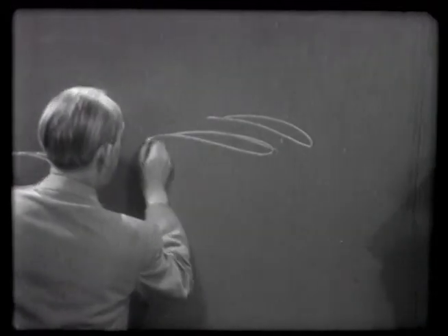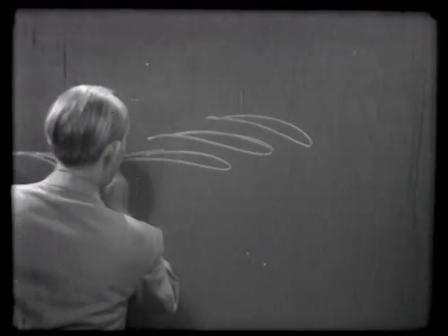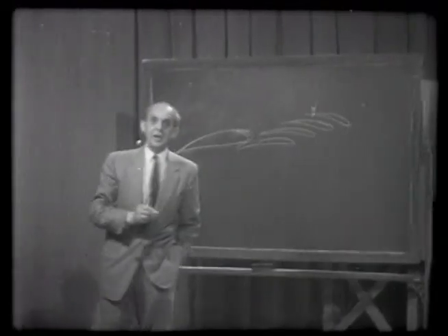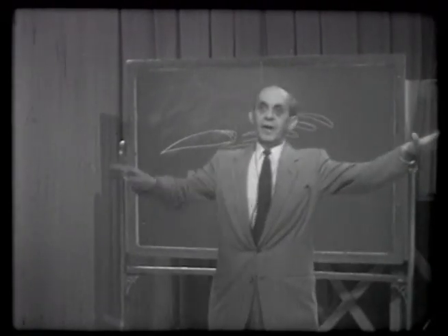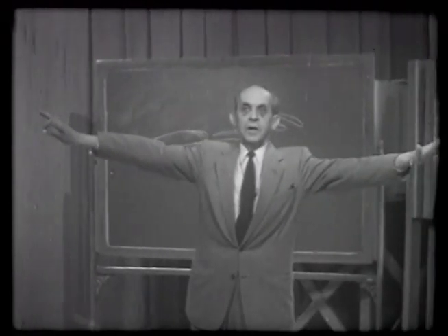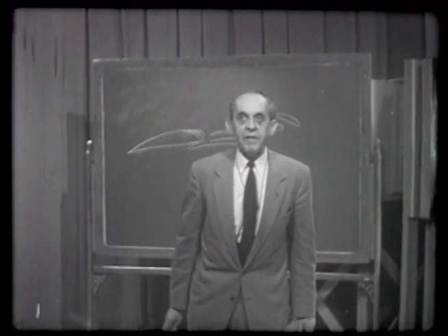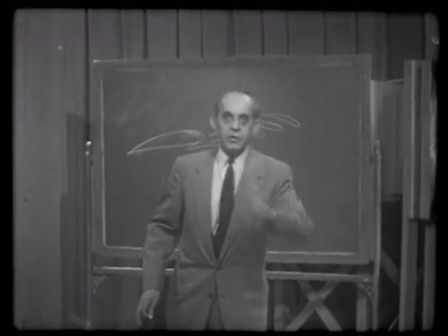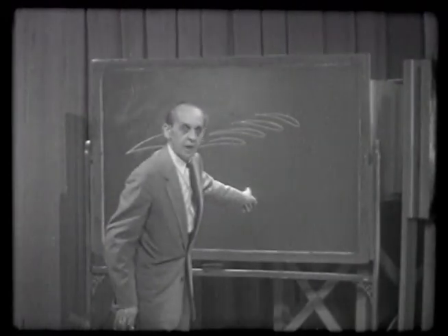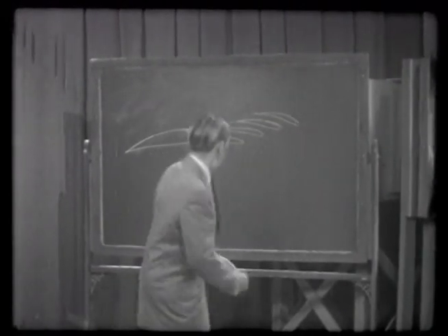But you have also wings where several slots are one behind each other. And remember what you have seen in nature. A bird has this in its outer so-called primary feathers. And he prevents the stall with the same method that we have today on the airplane.